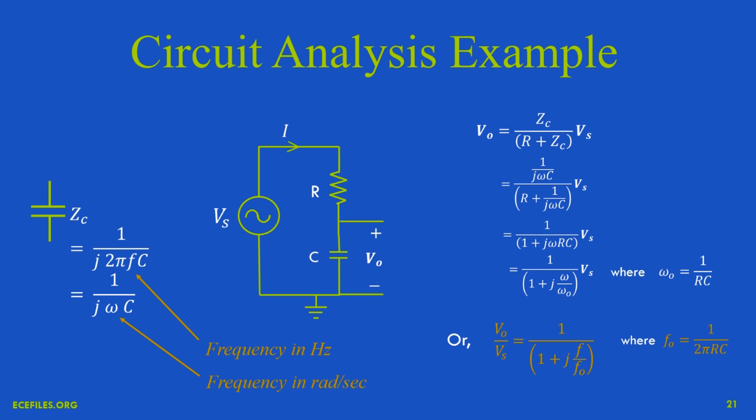All right, with the complex number and phasor machinery finally in place, let's do something useful. Let's analyze this circuit in detail. From previous episodes, hopefully you recognize this as a voltage divider, except in this case, instead of a resistor here, there is a capacitor. And the useful thing is that the capacitor's impedance changes with frequency. So at low frequencies, it may be very big in magnitude compared to the resistor value here. And if it's very big, you don't get much voltage division, the signal goes on out.